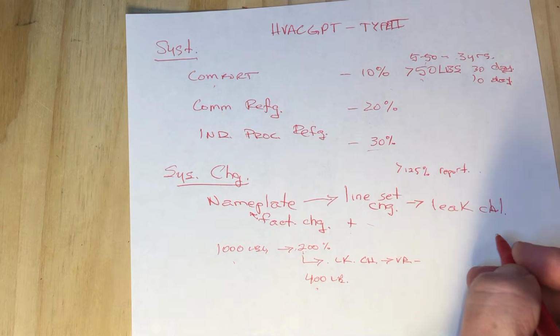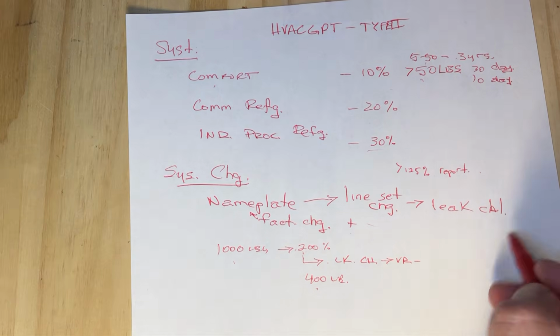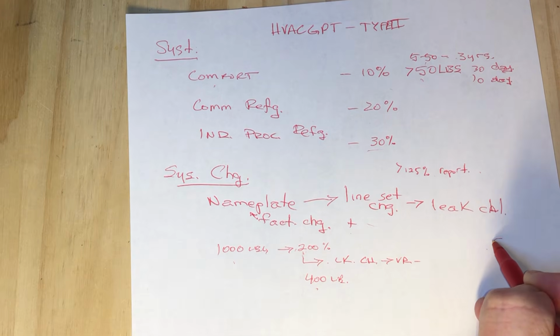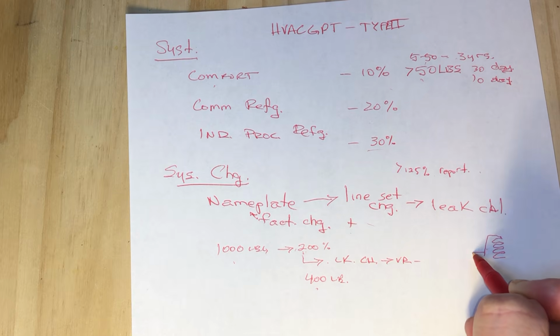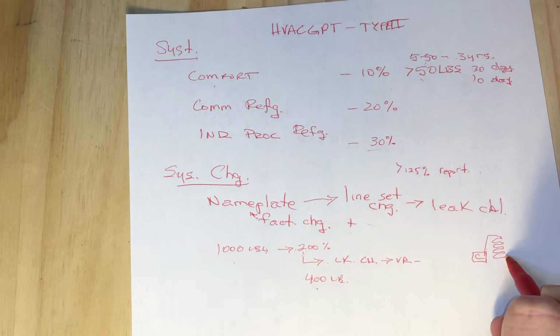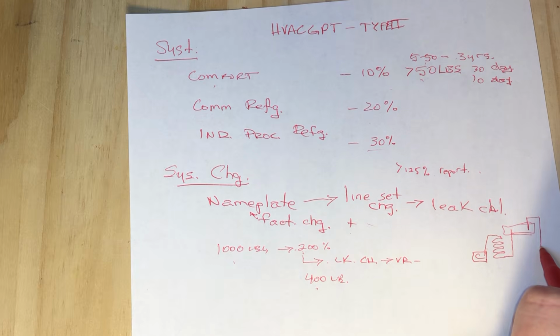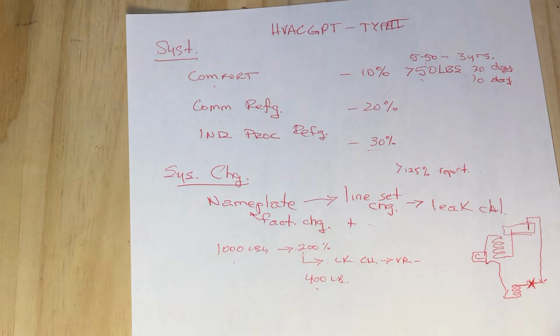But let's take a look at the system. I like to draw a few systems for the students. Let's say you've got a condensing unit here, right? And it's fed from a compressor over here. You've got your compressor, and then sometimes they feed into a receiver tank for these bigger systems, and there's a dip tube, and the receiver tank feeds down to a metering device, some sort of expansion valve, before it goes into the evaporator, before it's fed back to the compressor. Okay, so that's your AC system there.